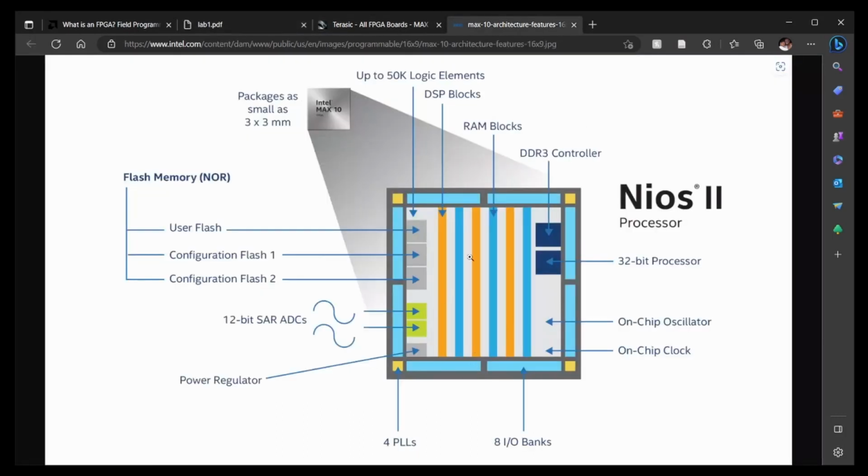So we've mentioned that we have an FPGA. It's simply an array of gates, an array of logic elements interconnected in special ways. Now, how do we make this particular FPGA do a particular function? Well, we need to tell it how to do that, and we do that through a hardware description language. It is called a hardware description language because really what you are doing is describing what the actual hardware should be. So, for example, you could say, I want to connect an AND gate to an OR gate. I want to connect it in this specific way. I want to connect this clock to so and so place. I want to connect this and this and this in this way. So it's a description of what the hardware actually looks like.